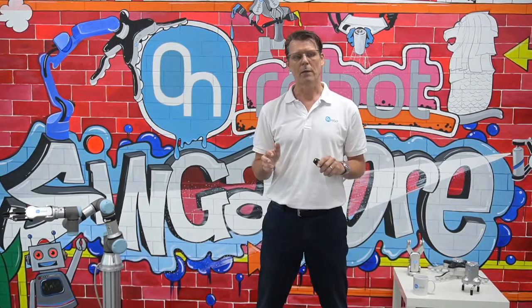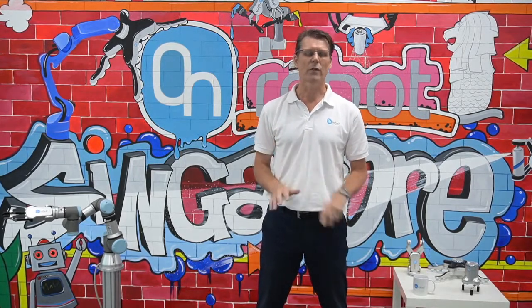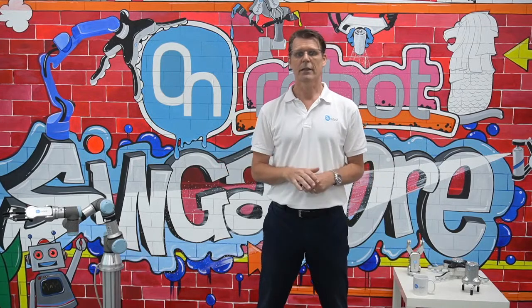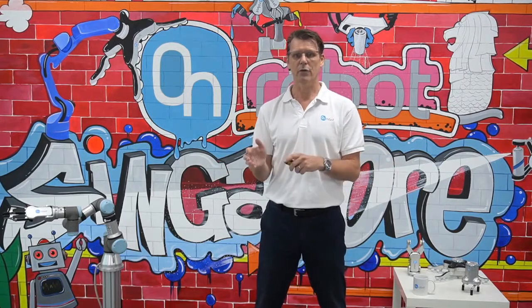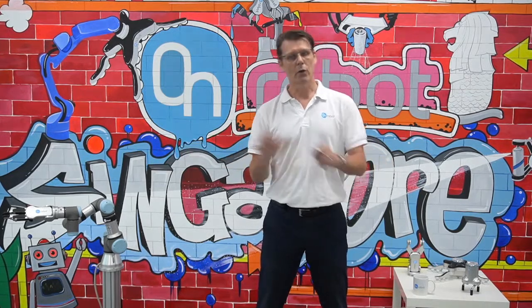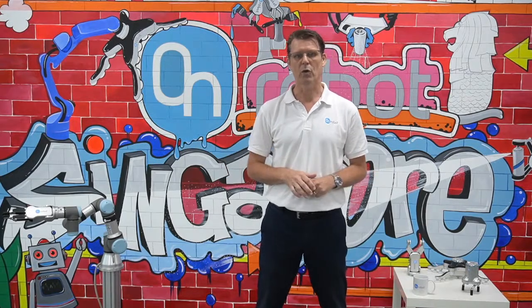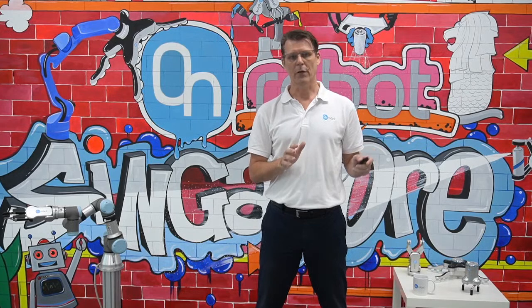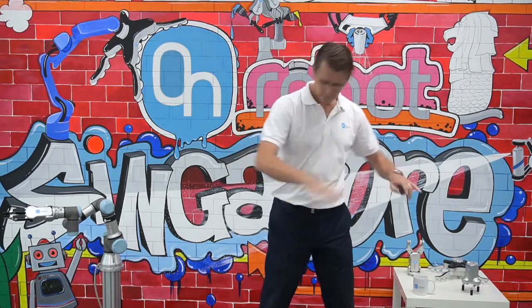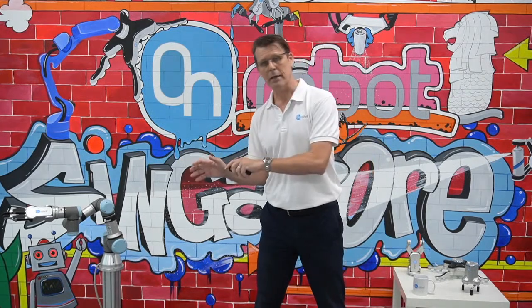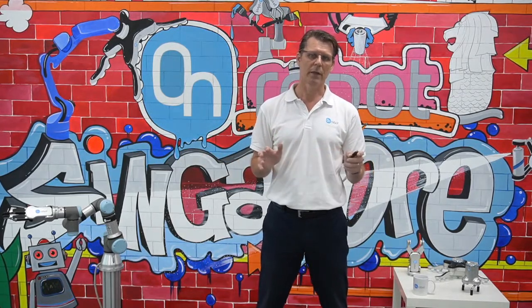When it comes to collaborative automation, there are really four types we're talking about. The first one we call coexistence. That's where the human and the robot work alongside each other without a fence, but with no shared workspace. That is actually the most common type of collaborative application at the moment. The second one we call sequential collaboration, where the human and the robot are active in the same shared workspace, but their motions are sequential. So they do not work on the same part at the same time. That is the second most common collaborative application setup in the industry today.